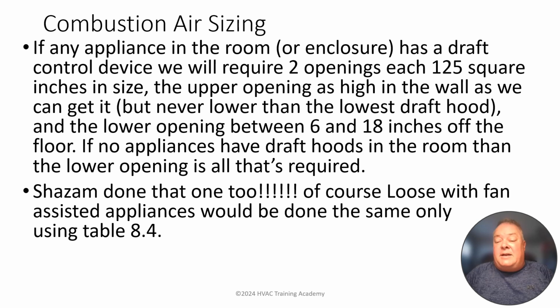Now, if they're both fan assisted in that room, we only need 1 opening, right? We'd only need a 125 square inch opening between 6 and 18 inches. They call the lower opening the combustion air opening. They call the upper opening, when you have draft hoods, a ventilation air opening.